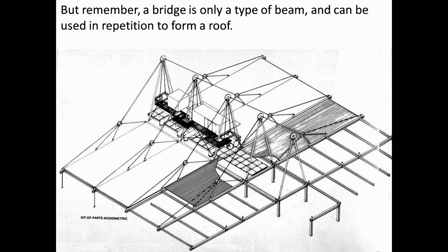Now the reason for doing it in this case, of course, is that underneath this roof structure, it's not showing the outer cladding yet, of course, but you need a big open space. You don't want lots of columns getting in your way. You need nice big open plan areas, and that's the reason for hanging everything off these central masts. Okay.